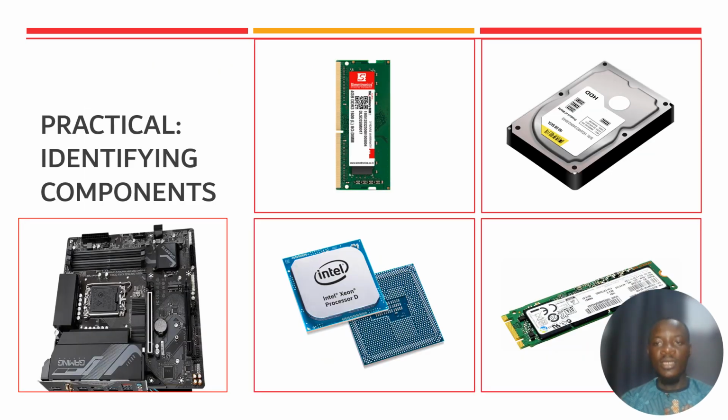Then the practical exercise. We will identify these components in a real computer. Make sure to ground yourself before you start doing this on your computer or any computer device you come across. Be careful how you handle the RAM especially, because it is sensitive to static charge. Be careful how you hold the RAM, because these pins over here are very delicate, so you need to be gentle to avoid clearing the information out of it.